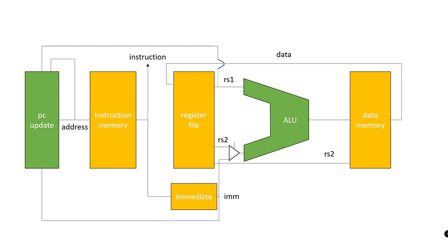The placement of registers must first break any combinational cycles in the data path, which is a basic functional requirement. Registers also help to balance the delay across the stages. The clock period is determined by the longest delay from any register output to any register input. Registers can be moved across logic to equalize delays. In some cases, registers are added to break a long delay path.